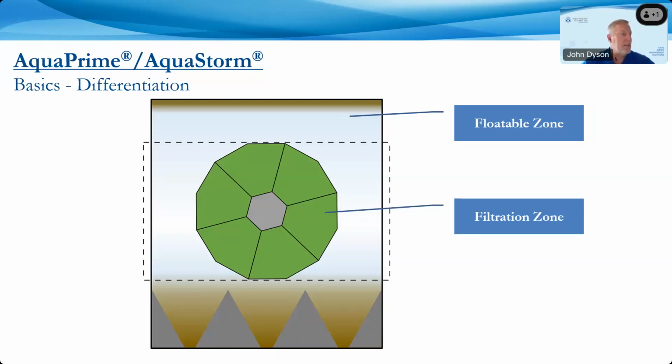A core of the work is still done by the cloth media, and the cloth media is a unique thing, with the ability to clean in such a difficult application of raw primary influent coming in there. And we also made changes to the settled solids in the system. In primary applications, we have settled solids that are readily settleable. I always like to use the analogy that in a primary clarifier, particularly a horizontal one, we make them deeper at the front end where the hot solids are coming in initially, because a lot of those settle out very rapidly in that location, the first 10 to 20%.